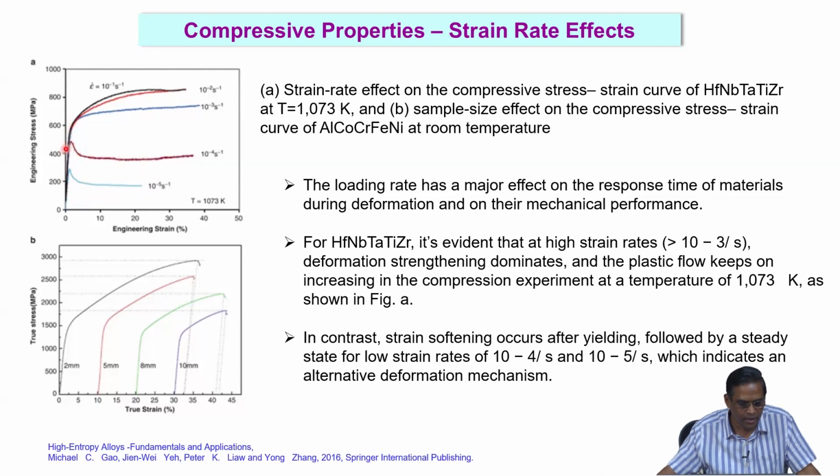But at these strain rates, it does not show any dip in the yield point, it just continuously increases at the high strain rate. Okay. So, though these are all the same material, the strain rate shows a different kind of stress strain behavior. That means the mode of deformation is significantly changing from the low strain rate to the high strain rate.